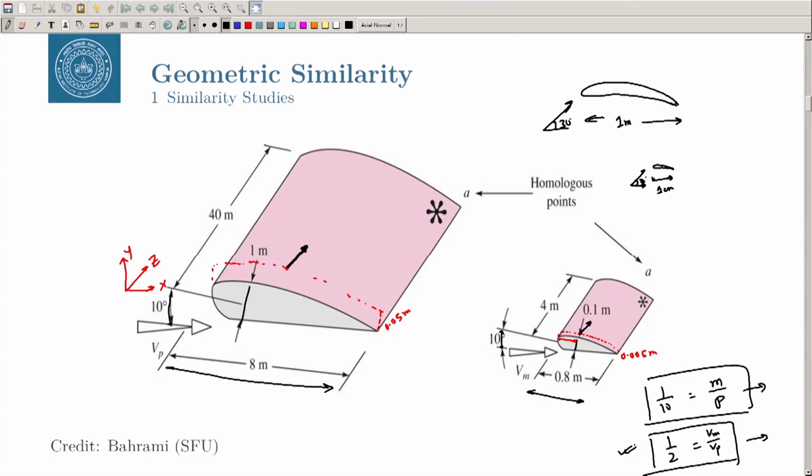a lot. Okay. So, you should not be comparing, let us say you have a critical Reynolds number. The critical Reynolds number is the Reynolds number at which the flow basically transitions from a laminar flow to a transitional flow and then eventually to the turbulent flow, right. So, let us say you are talking about a number which is in the transitional regime, then it will be very difficult to correspond a prototype to a model unless the prototype is also in the same regime, right. If we are talking about laminar, both should be in the laminar regime. If we are talking about turbulent, both should be in the turbulent regime, right.